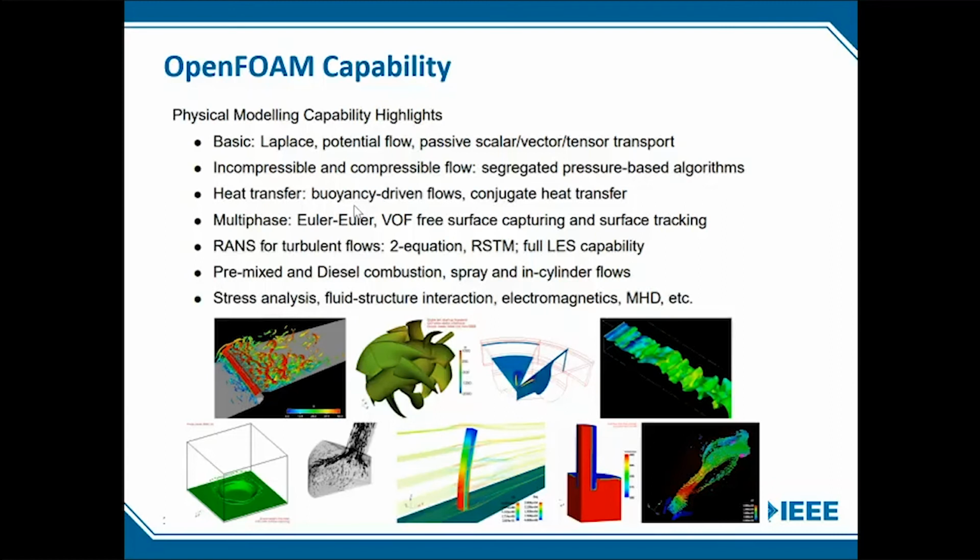You can basically tweak the equations, add more terms, remove some terms, and that is why it's much stronger, because it's open. There's nothing hidden from the user. But on the other hand, in Fluent, you really don't know how it's solving your problem in the background. You cannot see anything. You cannot tweak your governing equations. Navier-Stokes will be solved. You cannot say take out all the terms on the left hand side of the equations, which I can do if I'm using OpenFOAM.